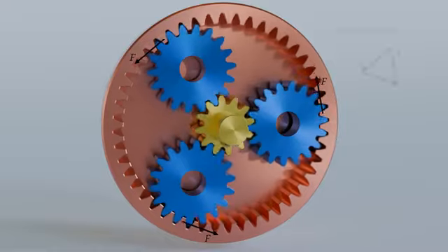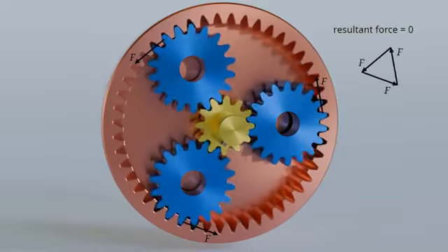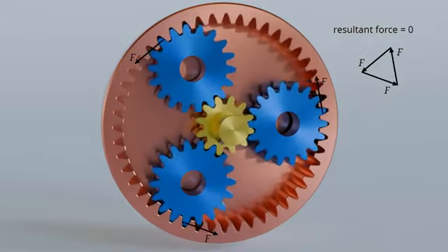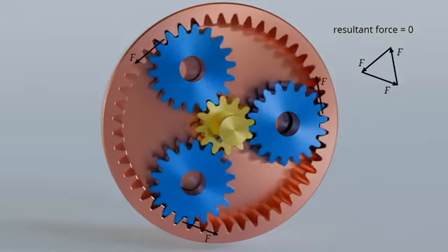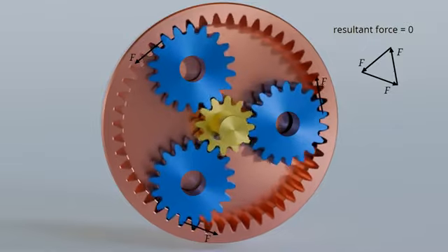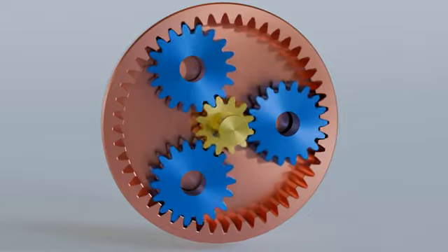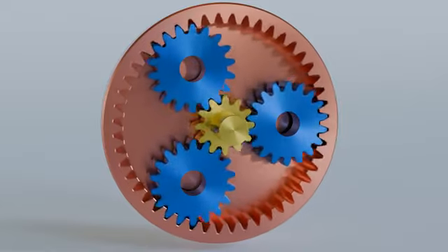In the case of three idler gears, the drive and output shafts are no longer subjected to bending, but only to torsion. At the same time, the circumferential force generated by the torque of the drive shaft is distributed over a total of 3 gears, reducing the flank forces of each gear. This significantly increases the maximum torque that can be transmitted. In principle, this gearbox is already the preliminary stage of a planetary gearbox.